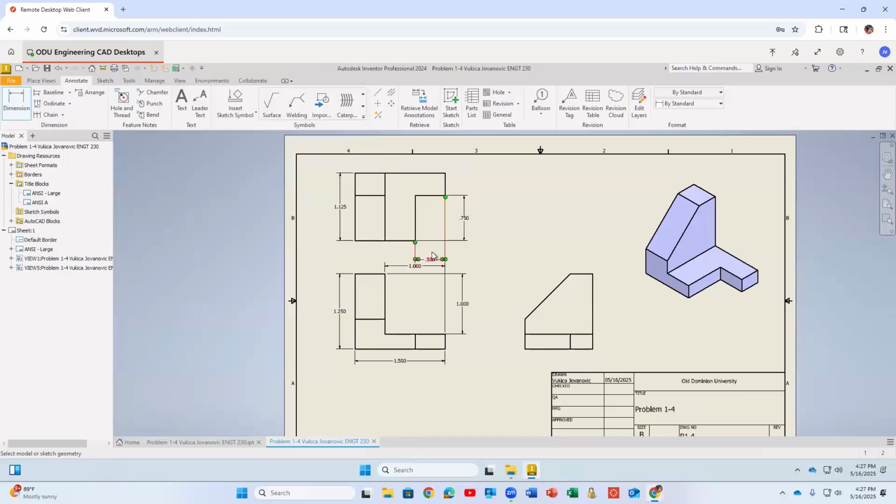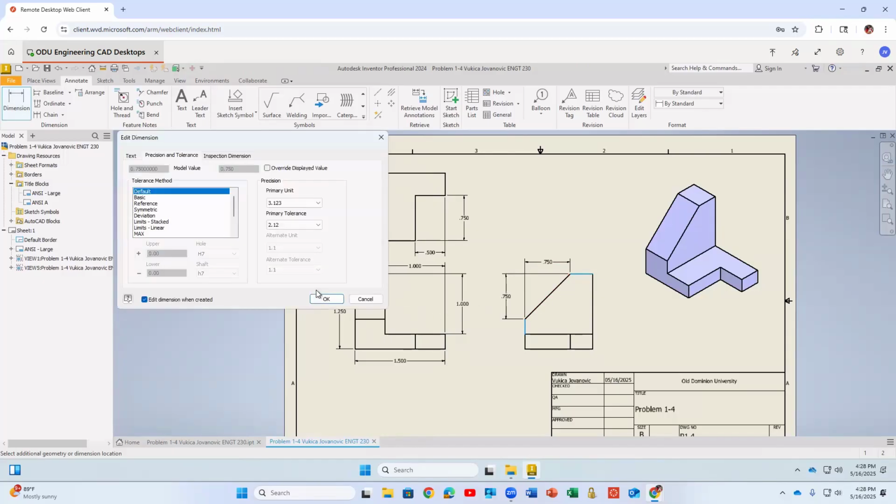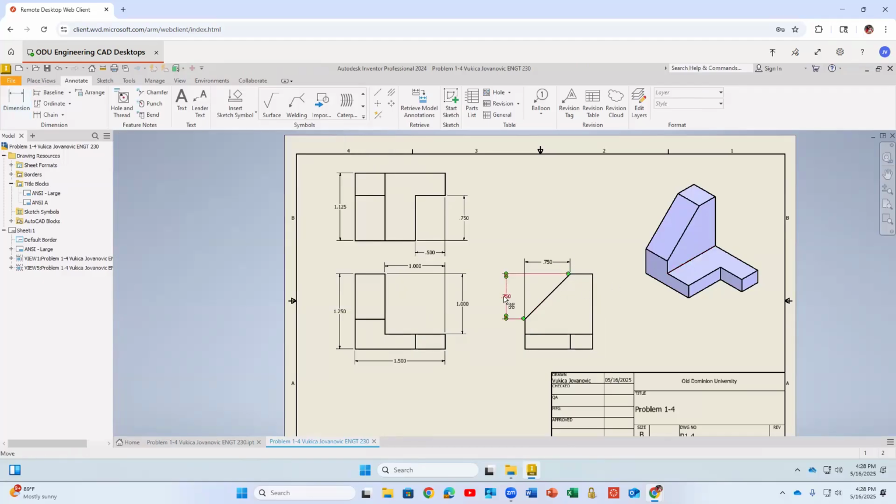So for example, now it's kind of crowded. So I'm trying to put it, so that's one. Or you can make this drawing for somebody from quality control so you can measure what is left. So you see, in this way, I'm saying, please remove that. And here I had a chamfer, they were telling me these two dimensions. So in this way, I'm telling somebody who's working in material removal what they will need to remove. So that's one way to dimension. There's not a single way to dimension anything.